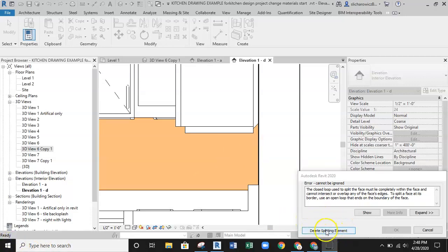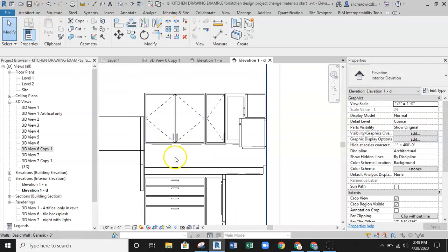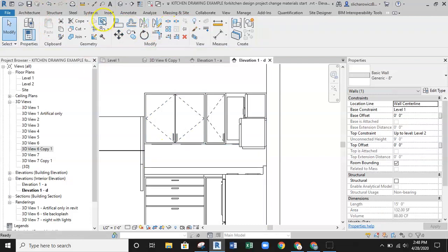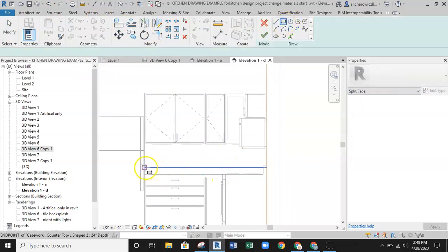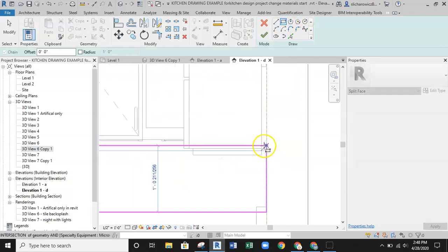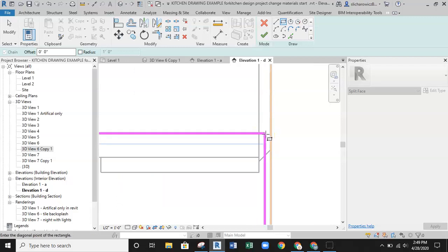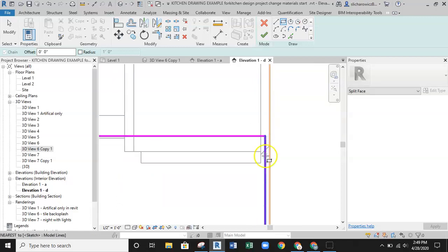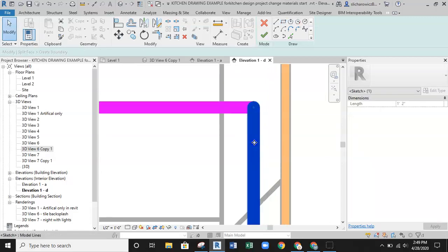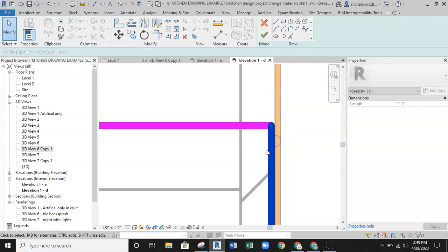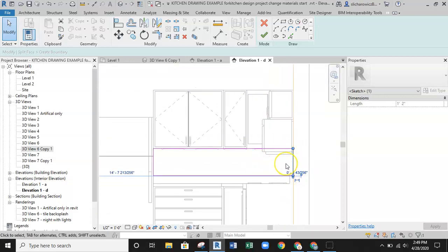The easiest way that I found to do is hit delete splitting element, and what we'll do is just do this one more time where I select the wall, I grab my splitting element tool, grab the wall again, and now I'm going to go ahead and do the same thing I did before where I draw that rectangle in, making sure I'm up here at the top, but I'm going to keep this a little further back away from this wall. Okay, so I put that in position, hit escape to stop drawing walls, and I'm going to zoom in and drag this really close to the wall. Not going to touch the wall, and really in a rendering situation you're never going to see that.